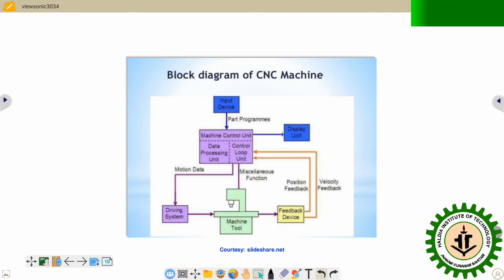In current days, you have your pen drive, so you can write your part program on the laptop, take it on the pen drive, go to the CAD/CAM lab, and transfer it to the machine. The machine has memory, so it can be downloaded very fast. Some input device is required, or the machine has an NC console through which you can also input the program data using the keyboard.